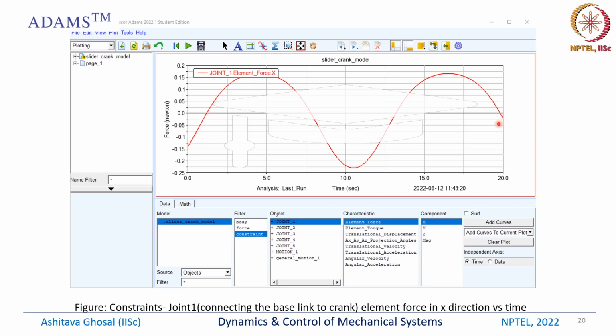So if I know this is the x component and the y component of the force which is acting at the joint, then I can choose the bearing. Similarly, I can find forces at other places, so I can design the link dimensions to withstand those forces. So although the Fx and Fy do not contribute to the motion, they are required for design.